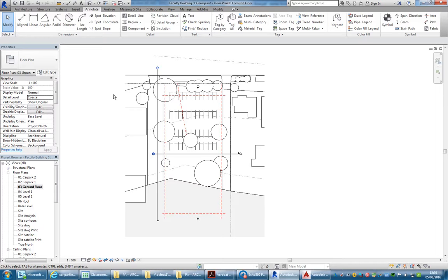And then, oh yeah, one last thing, to get the excavation done. What would be the first thing you'd maybe think about for your lowest car parking level? So, exactly, building pads, that's right. And would you do a floor on top of your building pad on that level? Yes, absolutely. So do a floor as well always. Don't just try and do a pad and put your walls on top of that. Make sure you put a floor above the pad, and so then you can set the pad to be the foundation instead of being the floor.